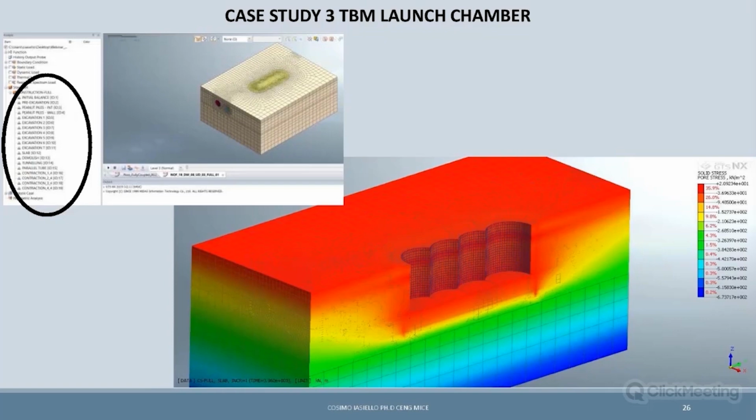It is the initial balance. And then little by little during excavation, we say, okay, right now your water table will be according to some position of drains. And we are going to have in this drain a flow of pumping, so negative, of, I don't know, minus 1 liter per second or 2 liters per second, depending on what our hydrogeologist is telling us.